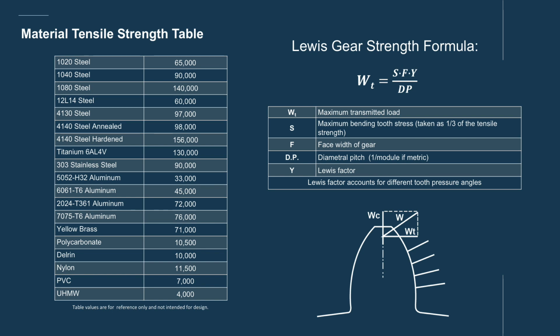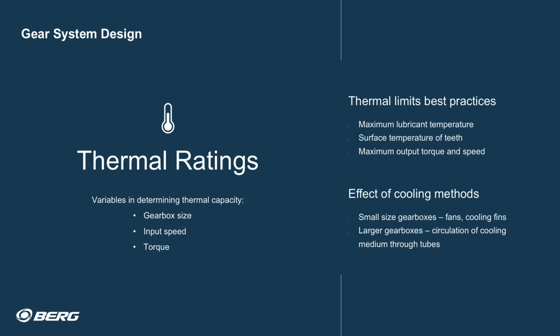That said, we like to use this tool as a quick way to help identify the pitch and width of a gear required to transmit a given force. Please note that this is based on force. If torque is given, it should be converted to force at the tooth using the diametral pitch. The design of a gear system also includes an analysis of the thermal performance.